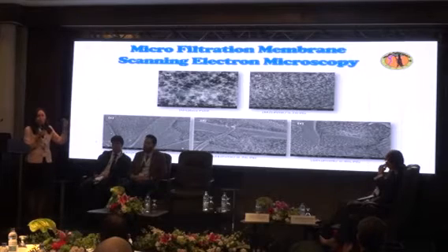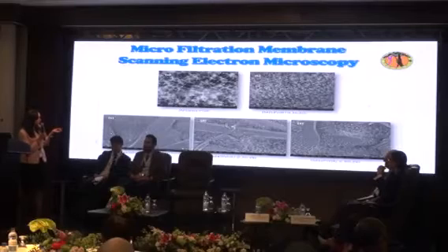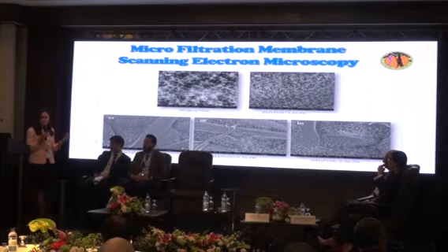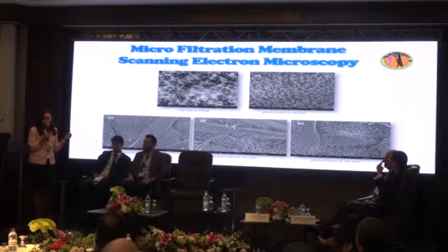So that's why, as you can see, it has larger pore size. Of course, it will permeate all the solution, all the water, and all the oil. So that's why we don't need it. And as you see, from the second picture to the 5th one, I used the PEI with different percentages to increase it and to see what's the effect of this new substance on improving the pore size and the pore quality of the microfiltration membrane in order to be used in this field. And that's why we can find that the best percentage of the PEI is for membrane number 3, which you can use at 0.5 weight%.